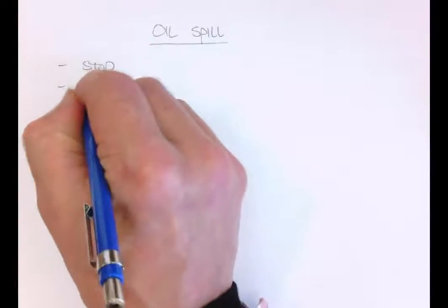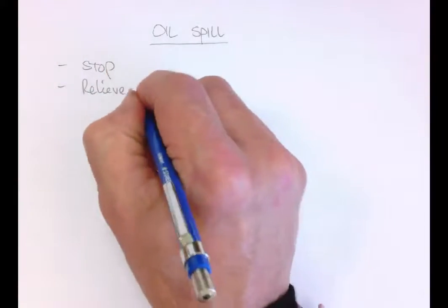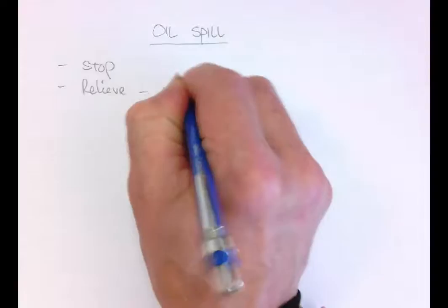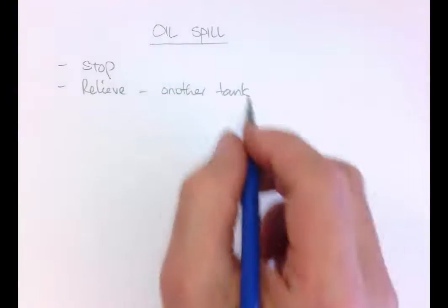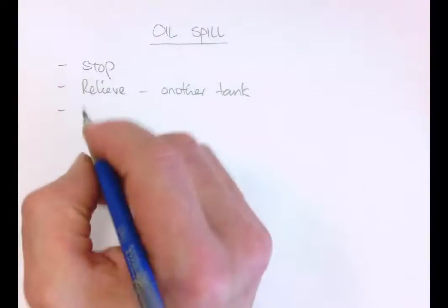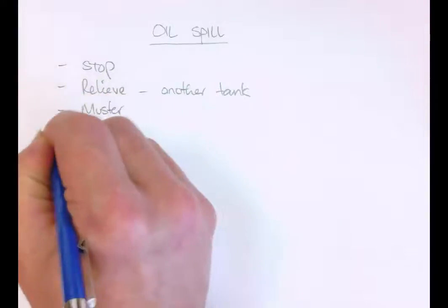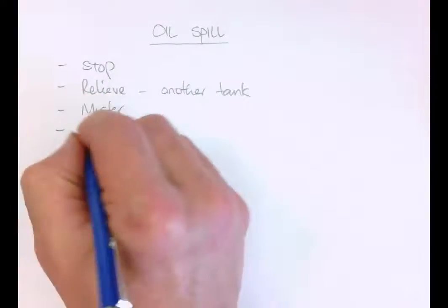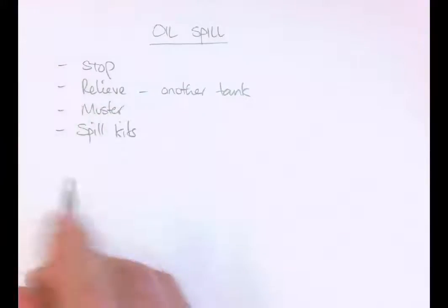We want to try and relieve the pressure on the fuel tank to another tank. So we can open up another tank valve just to take that pressure off, because it will tend to keep spilling for quite some time when it's under pressure. Okay, we want to muster and get all hands on deck, apply our spill kits, and look, if